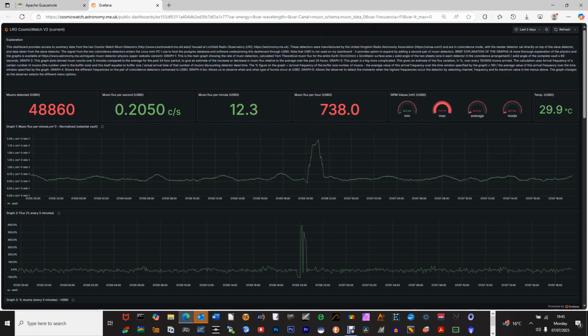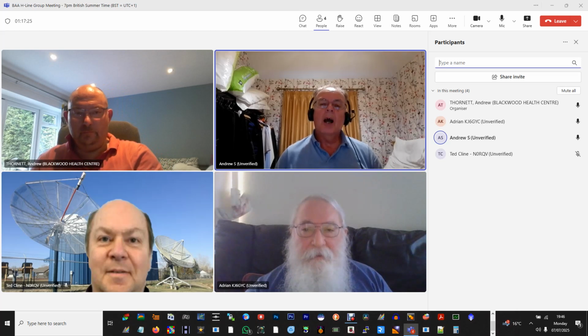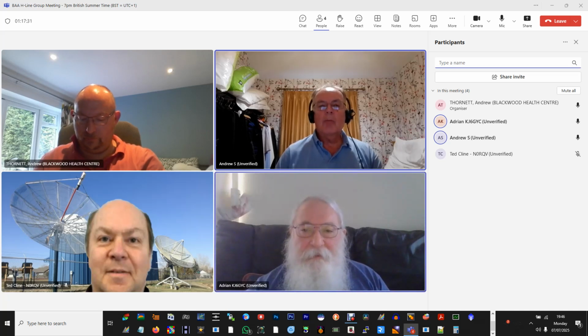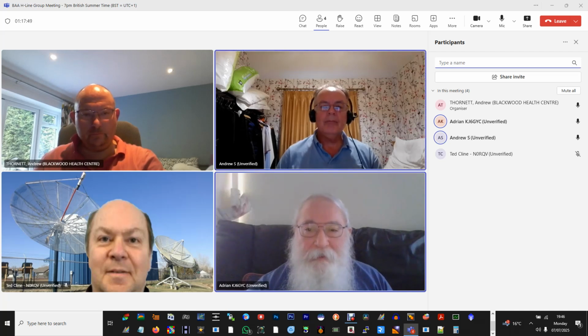Well, I wasn't intending on combining them. So you're just basically using a combiner? Yeah, I've tried independent amplifiers, treating them like interferometry, but I haven't really improved signal to noise. Oh, you multiply the noise the same way you do the signal. Well, true. Although the noise is random, so I don't think polarity would matter. And of course, a hydrogen line doesn't really have much of a polarity to it. No. So if you're doing hydrogen, that's not going to be any advantage.